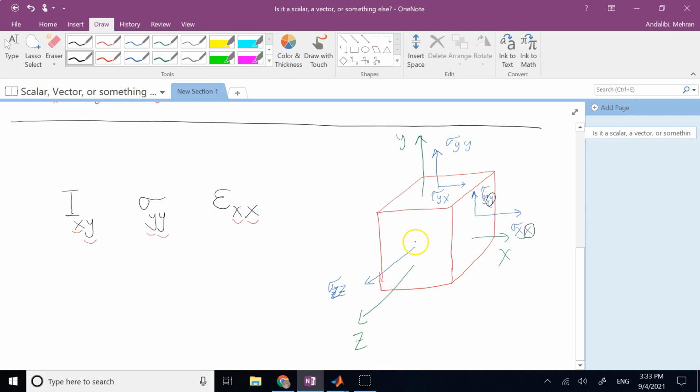So here, for example, if I have a stress like this, it is a shear stress tau because it's tangent to the surface. It is on a surface with normal z, but the direction of it is y. And if I have something like this, I call it tau_zx. And similarly, I can go here and declare this guy to be tau_xz. And here I will have tau_yz, right? So you need two directions. One is the plane, the other one is the direction of that stress element.